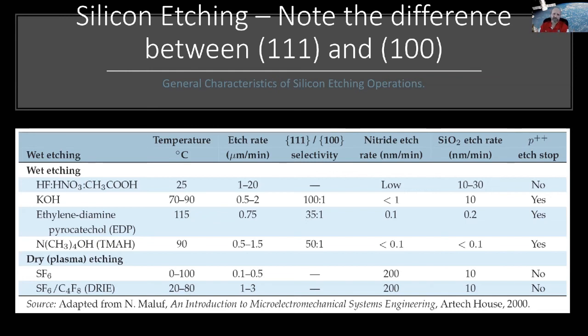We did some work one time and we thought we were using silicon nitride deposited wafers because they look a lot like silicon dioxide deposited wafers. So when we did our etching in the potassium hydroxide, after about an hour and a half, we lost the wafer. The wafer dissolved completely in the potassium hydroxide bath, which was kind of funny. So we put 6 wafers in and we ended up with 4 because 2 of them had the silicon dioxide as the masking material instead of silicon nitride. So you got to pay attention to what your wafers are.